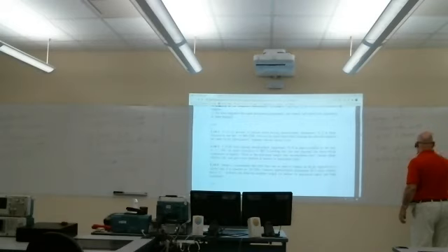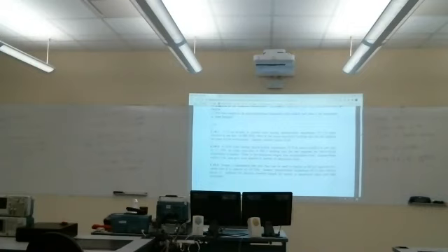And the phase velocity on this piece of coax: instead of giving us beta directly, it gave us the phase velocity, but they're related by the frequency. And then c is 3 times 10 to the 8th. So does someone have a calculator handy?